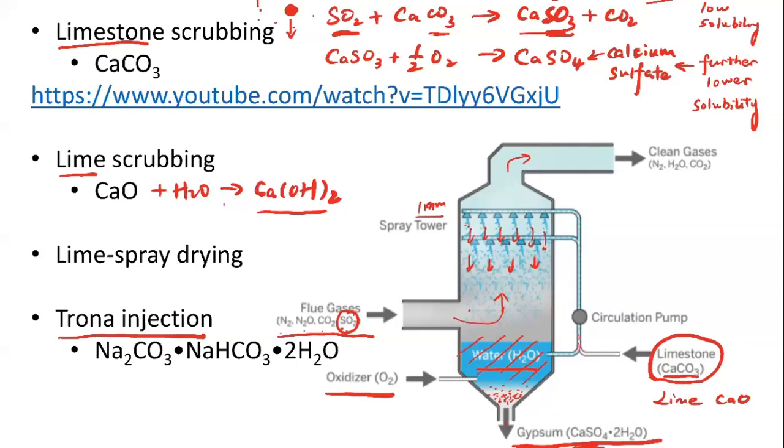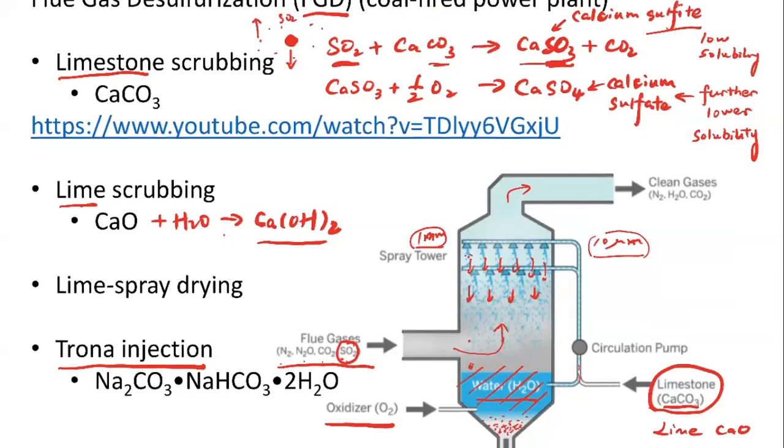If it's 1 millimeter large, then they're large enough that when they settle down to the bottom, they're still quite relatively large, although there's evaporation taking place, but they can still settle down to the bottom. Now let's say that instead of generating these larger droplets, let's change them to 10 micron droplets, okay? They're going to be very small, right? And by making them smaller, the reaction will also be faster, mainly because we're exposing more area of the solution to the flue gas there.